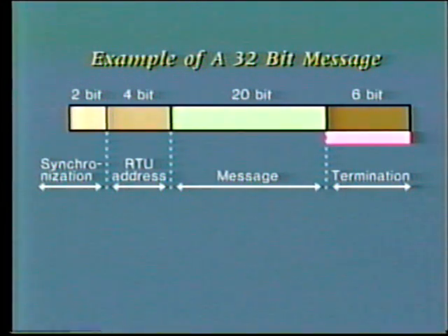Once the transfer of information is completed, the message will be terminated by applying a security code followed by a sign-off signal. There are several different types of security code applied, all with the objective of detecting any errors which may have occurred in transmitting and receiving the information. If the message transfer is incorrect, the operator will be alerted and a further attempt made at transmission.